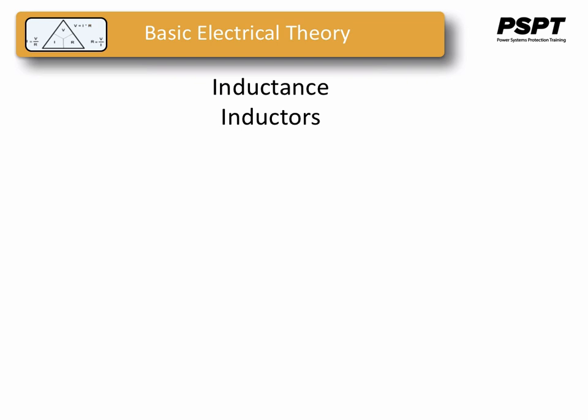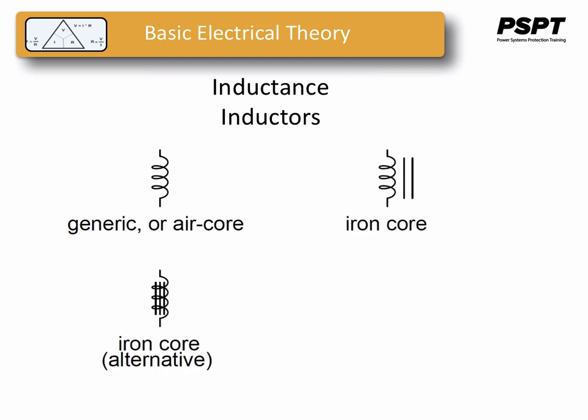The schematic symbol for an inductor, like a capacitor, is quite simple, being little more than a coil symbol representing a coiled wire. Although a simple coil shape is the generic symbol for any inductor, inductors with cores are sometimes distinguished by additional parallel lines to the axis of the coil. A newer version of the inductor symbol dispenses with the coil shape in favor of several humps in a row.